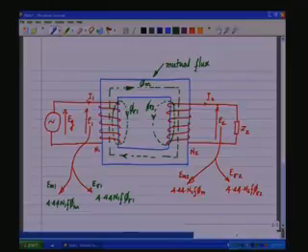What we can do is this: the flux here, which is phi 1, containing both the mutual and the leakage, can be split into two windings, one which links with the secondary, that would be the ideal transformer, the other which does not link with the secondary, but still there is a flux. So, we shall reconstruct it in this manner.